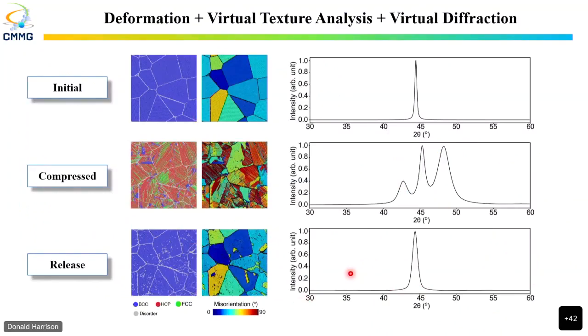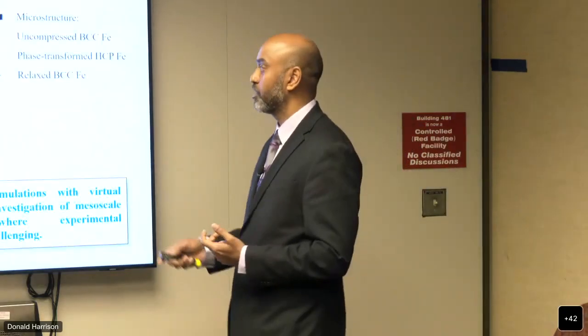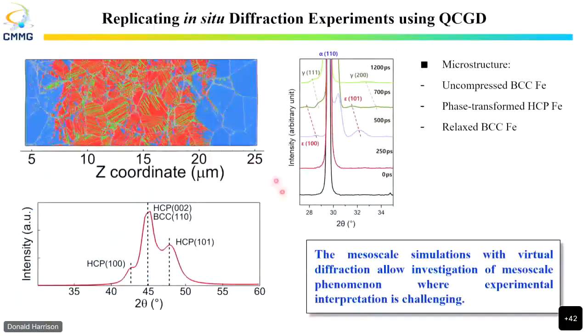And we can use the data sets to look at diffraction patterns and start quantifying how much of the diffraction pattern broadening is because of the phases or the fractions of the phases, and which variants, and how the twins are contributing to that. So one of the challenges I mentioned was that interpreting fractions from diffraction patterns is challenging if you have mixed states. So we can take the data sets where you have a partial release state, or a partially unshocked material with a shock compressed microstructure, and we can now generate a diffraction pattern for that.